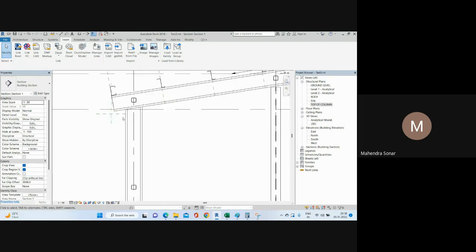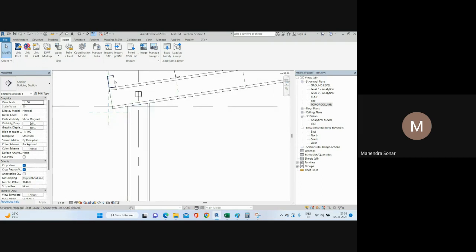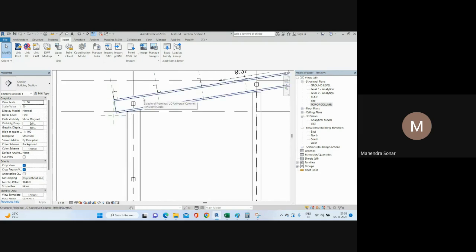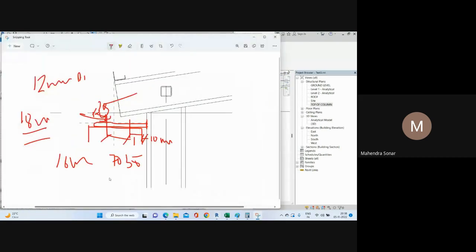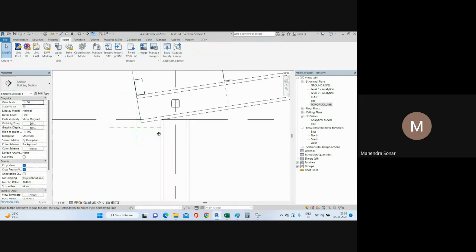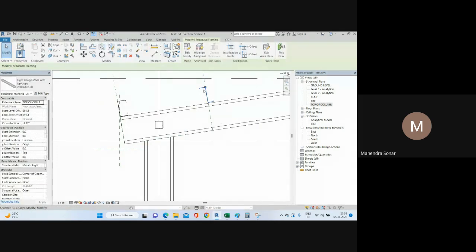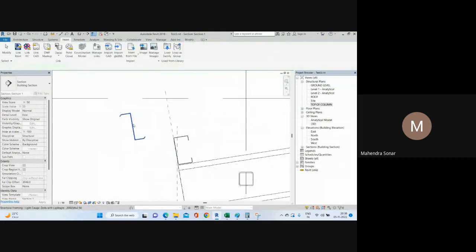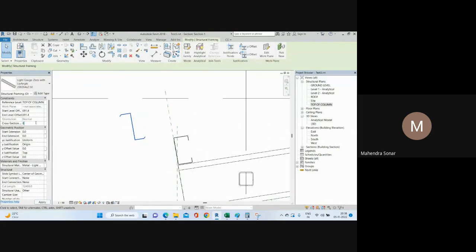Okay, so you need to add the C purlin here. If you add a Z purlin instead, you can go with that. So this is your plate, right? And you can just add your Z purlin like that, and your plate will come here. So if you design the Z purlin, you can go with that, right? So I will just copy this and paste, and you need to set the 0. Okay, and I will add 90 degrees here, so it comes here like that.